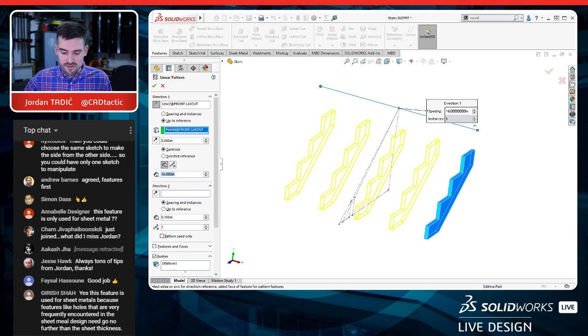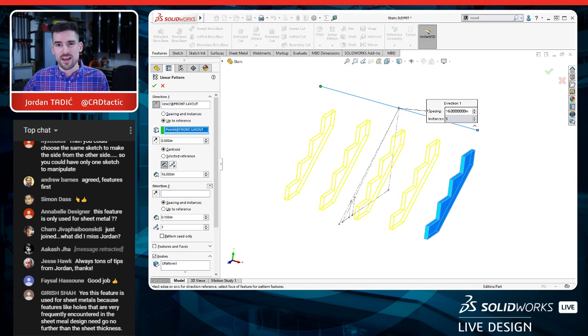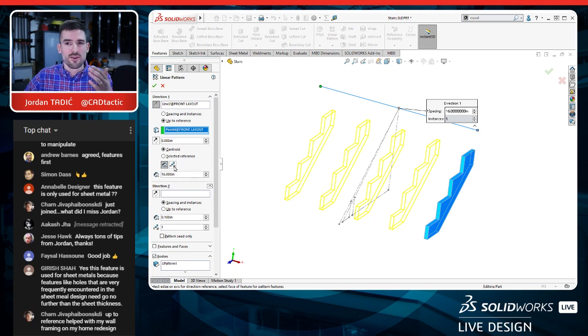Check this out. If I change this to 20, then SolidWorks will automatically calculate that only a total of 4 instances can fit in here. If I change it to 25, only 3 could fit. And if I change it back to the 16 that we need, it automatically figures out that we need 16. By the way, you can also specify the quantity and have the linear pattern tool calculate the spacing. So you go either way depending on what's more important for you. So I'm going to go ahead and hit OK.